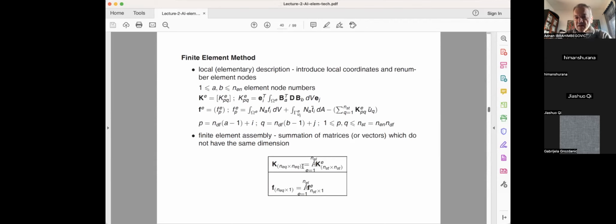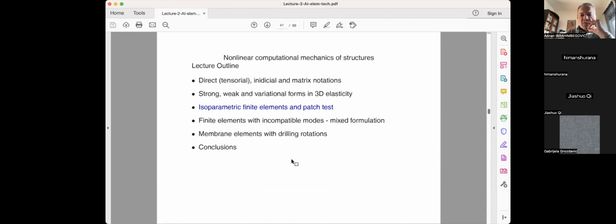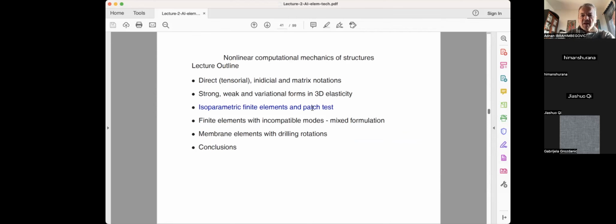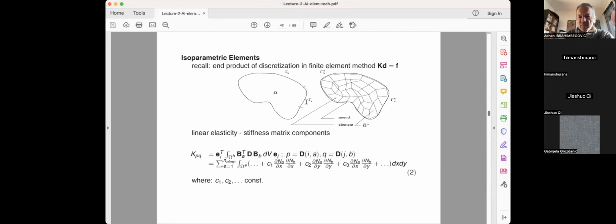So this assembly is pretty much the same as the 1D case. Again, the only difference is you have to enlarge the connectivity matrices to fit all these types of things. So basically, we will have to do that on the element basis. And this is what I wanted to discuss. So basically, the idea is as follows. I have my computational stiffness matrix and my computation of my external load vector for each of the elements. So I have to be able to define the particular contribution of this particular element.